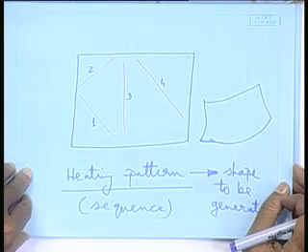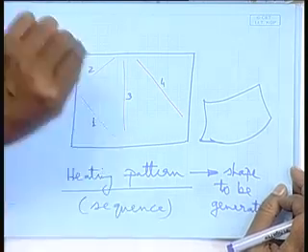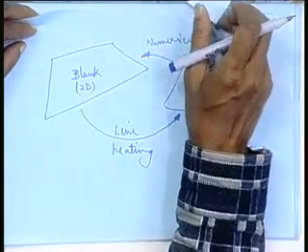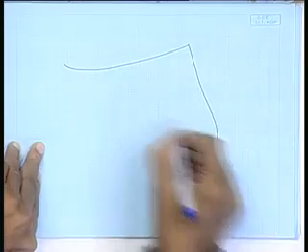So, once we get the heating pattern, we implement it by moving the heating torch, like we move the cutting torch in the same fashion, and you get the bent shape. Now the question comes of monitoring. How do you check whether it has really matched the desired surface, the desired patch? If we go back to a template, that will not be worthwhile. So here the checking would be, again, scanning by laser beam. Here checking is a little easier in that sense, because I have the entire plate visible.